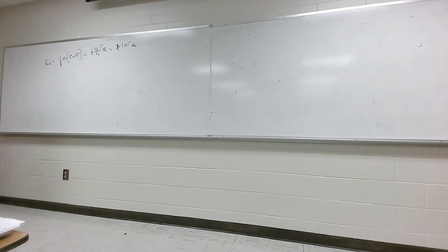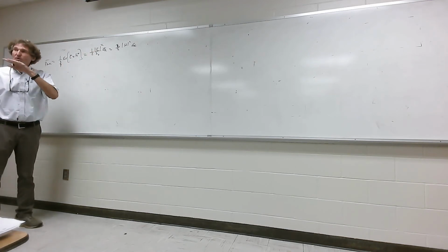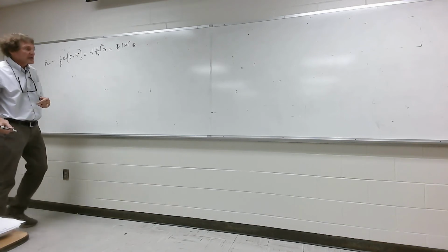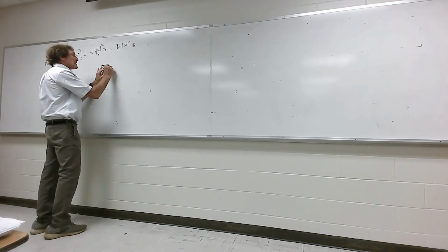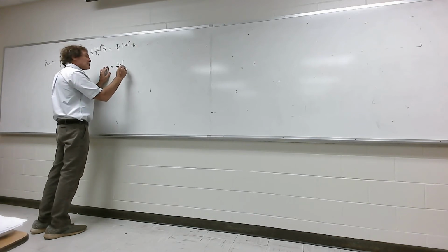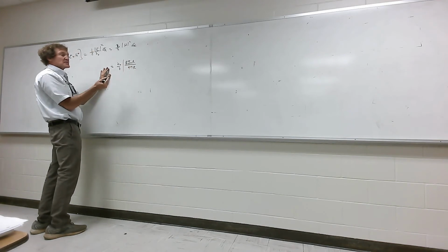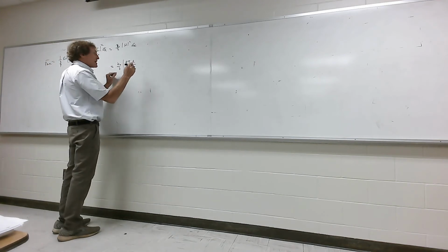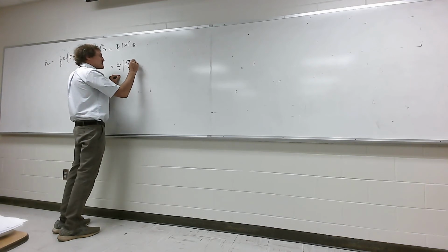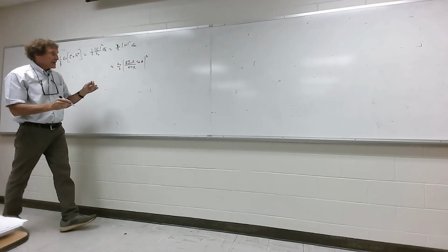I could go ahead and do this, but it will give me this or that, guaranteed for far field, and we're only talking about far field. So for P_av here, if I do this one, I get eta naught over 2. Now the H field was what? It was beta times I naught times L, over 4 pi r. Remember, it's going to be a magnitude, so the phase term you can forget about. Then you're going to have sine of theta. And this is only the far field term. It would be a_r.